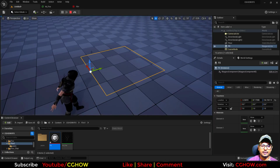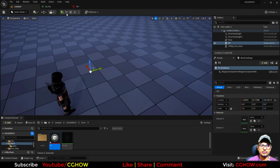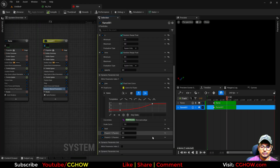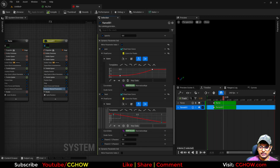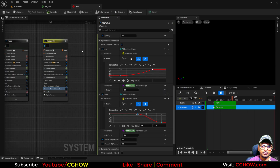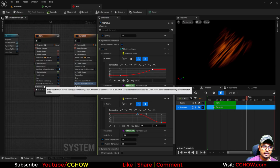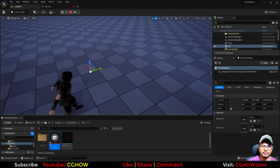So if I play, no heat distortion, and if I make this 1, there is this heat distortion. So you need to make a curve, and that would be like after 0.5, it should be 0. So if I play now, you can see it's fading properly. And in this one, in the flame, I will make this 0 by default. So they will be just separate things.